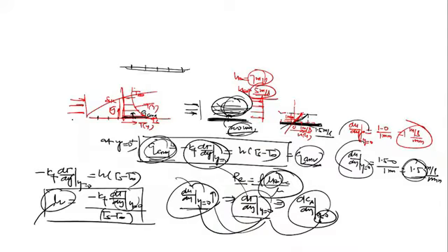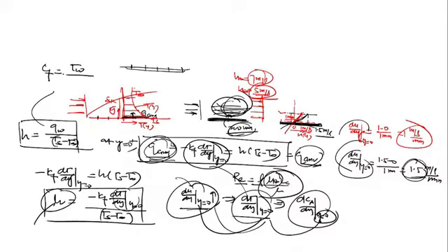I told you in fluid mechanics, friction coefficient is defined as tau_w. And h is equal to, my dear student, q_w, the heat flux to the wall, upon (Ts minus T infinity). It's analogous to the friction coefficient, that was tau_w, the wall shear stress. This is the wall momentum flux and this is the wall heat flux, and this was half rho u infinity square, and here it's the temperature difference. Clear?